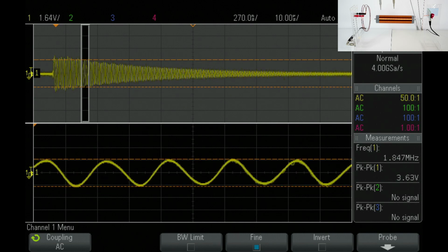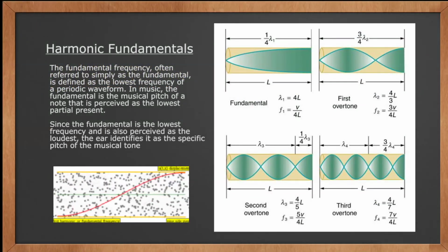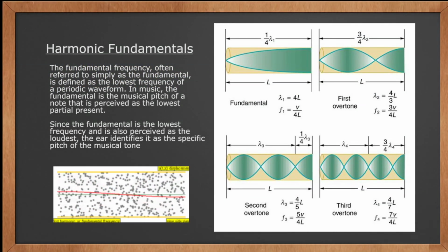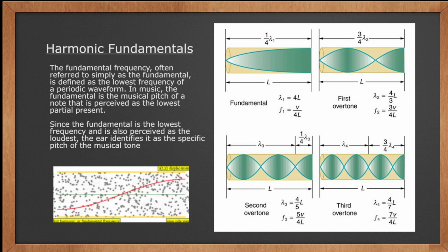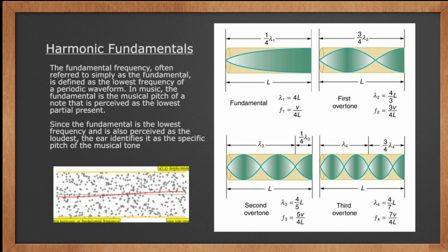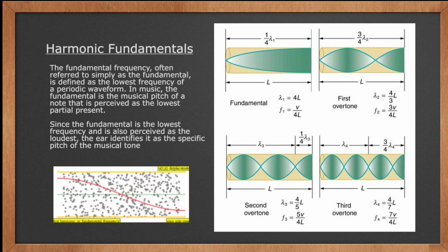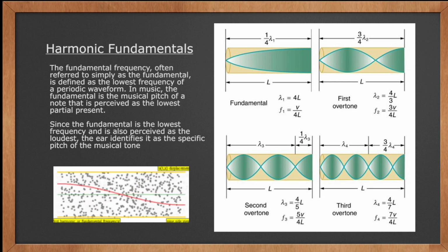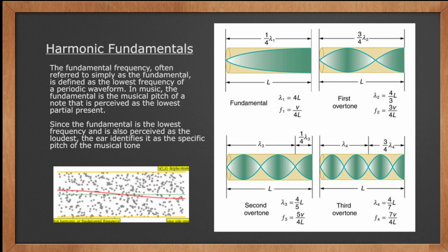Now let's go over the fundamentals. Here on the graphics on the right side you see the first fundamental on top. The quarter wave on the right would be visible when the coil is grounded. If unterminated, we see the wave fluctuation at the bottom left, where the center of the coil is close to zero. This would indicate a reflection wave with a node in the center and antinode at the end.